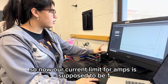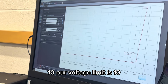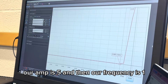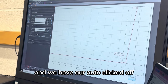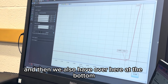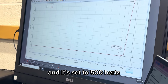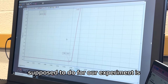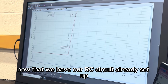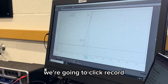So now, since we already have our Capstone set up, we changed the signal generator. Our current limit for amps is supposed to be 1.10. Our voltage limit is 10. Our amp is 5, and then our frequency is 1. And we have our auto clicked off. And then over here at the bottom, we have our voltage current sensor, and it's set to 500 hertz. So the first thing that we're supposed to do for our experiment, now that we have our RC circuit set up, is click record.